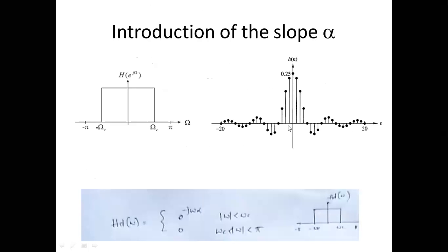What is this taper thing? What the author is trying to say is, if you select the values from the left with a magnitude of 1, select the values on the right with a magnitude of 1, and then suddenly cut off the values on either side, that's not a good idea. Instead, a better idea is to have a taper, a gradual change in amplitude. Say you have 1, then 0.95, then 0.9, then 0.88, then 0.86, and so on. Go for a higher order, but do this gradually.